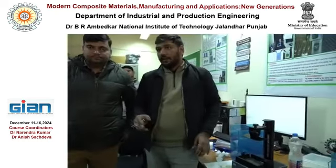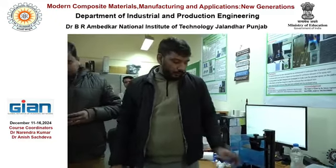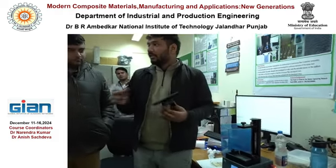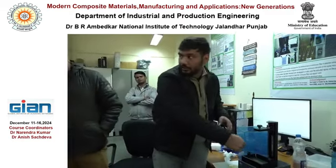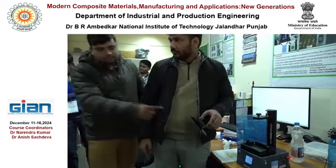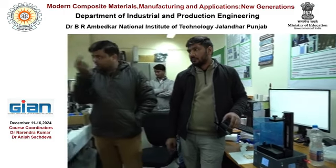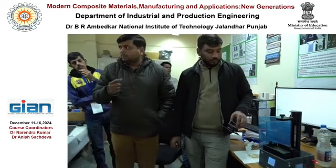Means that process that I have shown. You have to load the .dlp file, and you have to put the resin in the vat. Then after that you have to clean the platform. You need to clean it so that the material gets stuck after UV light falls from the bottom. The UV source is there, UV light at the bottom, right? So when it is switched on, this area will be exposed under the UV light, and we have already prepared the program, so that it will switch on only that particular selective region. For the selective region only, right? So that material will be cured automatically.